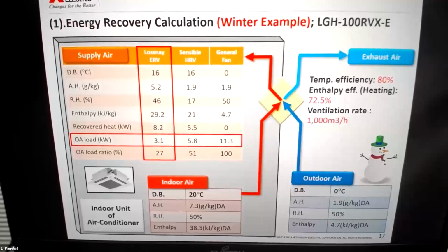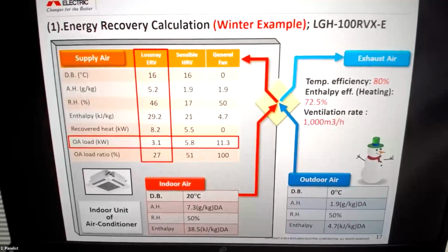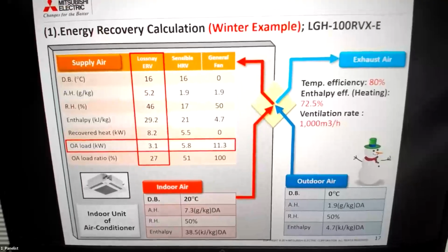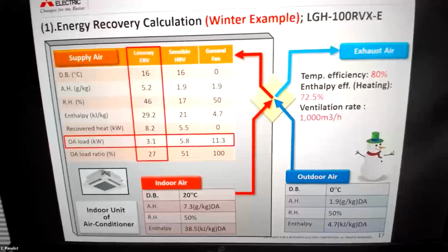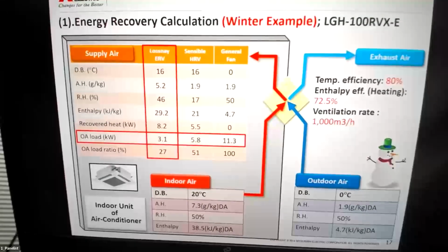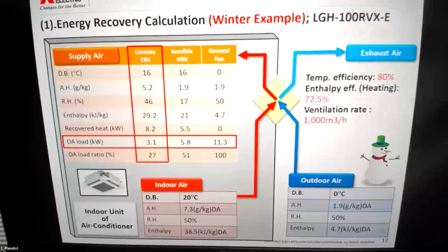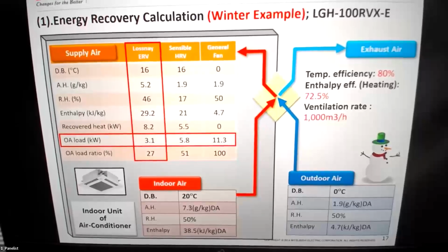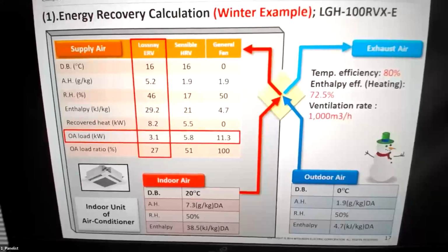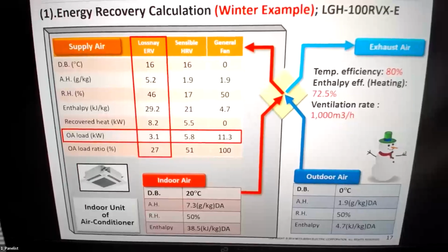Wet and freezing and dripping of the water might happen. We need to avoid that. Therefore, we have some limitation. Please use this unit down to -10 Celsius, but protection for -10 with intermittent operation, self-protection control is adopted.